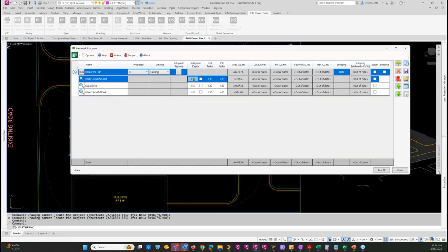So I can give my polyline an elevation, or I can do it right here. So 2 ways of doing it. When you create the polyline, you give it an elevation. It's simply an elevation from the top to your subgrade. And they can have all different elevations if we like them to.